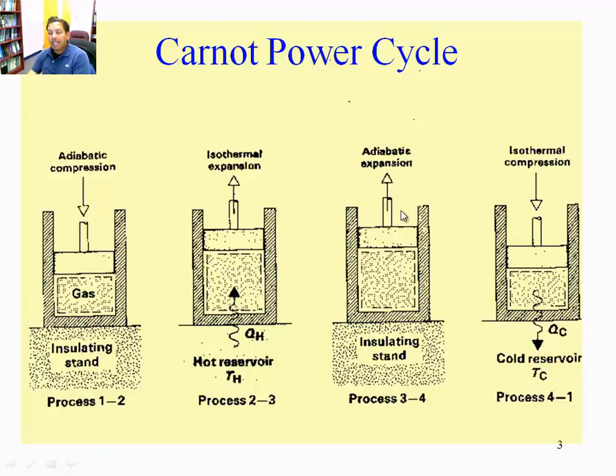So there's an adiabatic expansion, insulated. There's no contact with another reservoir, and there is no heat exchange in or out of the system. And then there is an additional compression after the system has expanded completely. There's an isothermal compression in which the system is placed in contact with a cold temperature reservoir at temperature Tc, and therefore the system rejects heat to the surroundings.